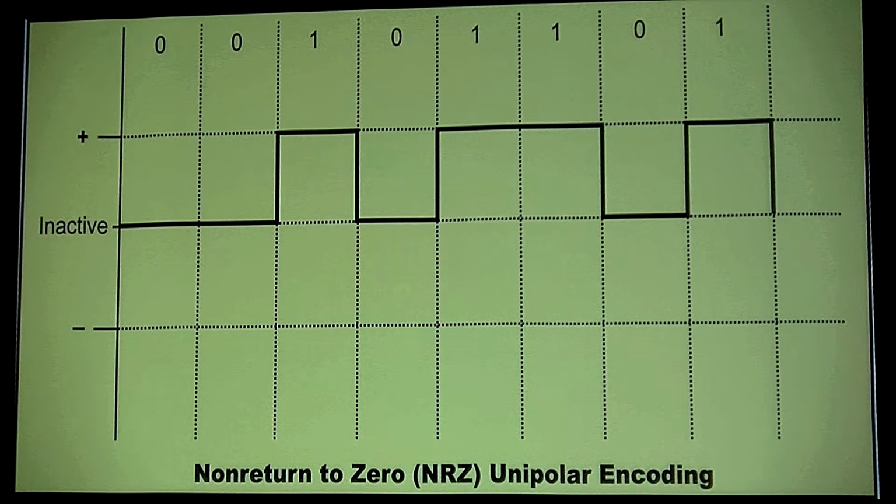Now I go to something called non-return to zero. Now what this means is I can stay low or I can stay high for multiple bits. Now when you start to see that you have multiple bits, we got to really think about this. So if I needed 10 bits sent, we sent 10 in a row, but I don't have any edges to resynchronize the clocks on, and these clocks are having timing structures, can you start to see it isn't going to work? I can't go 10 bits.